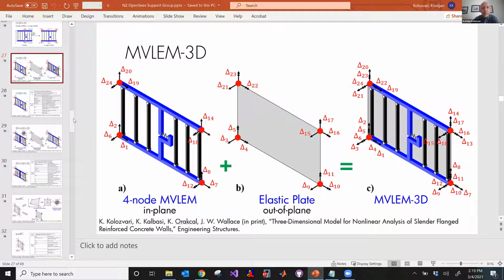There's no particular parameter that you put in for FRP, but you would have to find a way to modify the material properties or any other input parameters to mimic the effect of the FRP. But it's certainly possible. I'm pretty sure that's what engineers do in design as well. I mean, there is no FRP material or something like that.